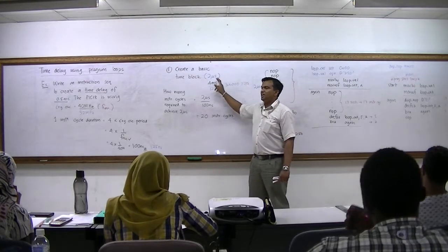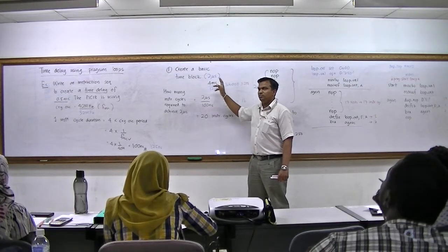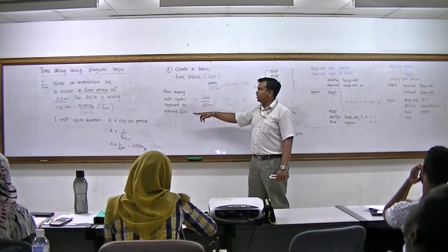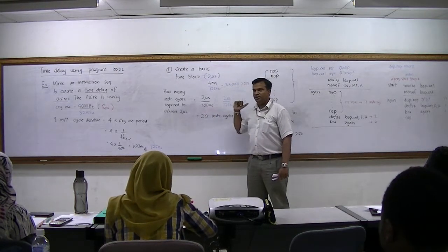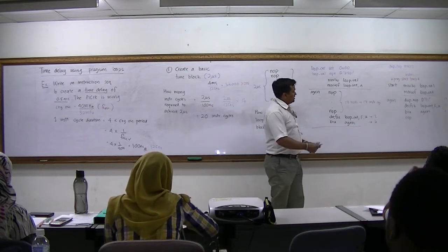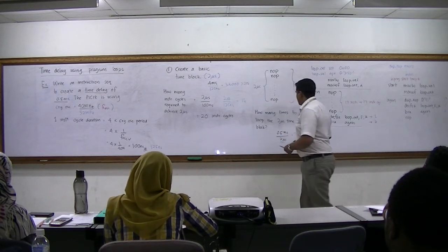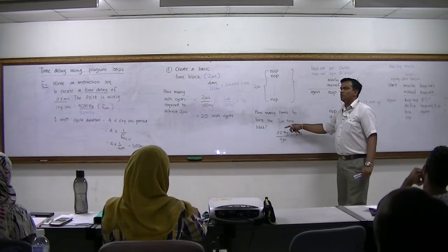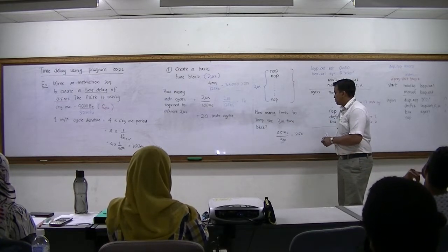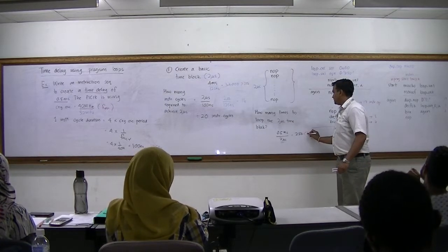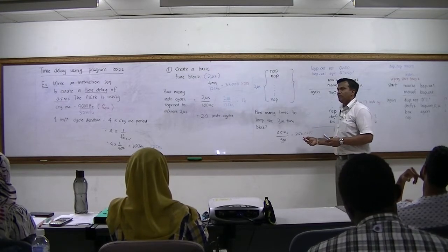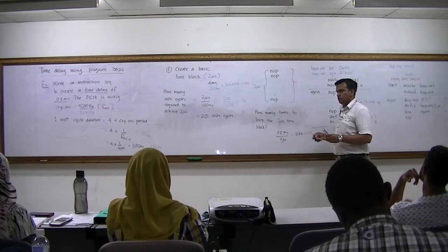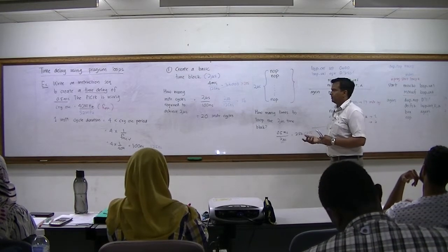That this one, the basic time block, you can choose any value that when you divide with the one instruction cycle, you get a value which is less than 255. That is one limitation. Another limitation is this one. How many times that you can loop the basic time block, this one also must be less than 255. If more than 255, then it will be nested loop, which we will see tomorrow morning.